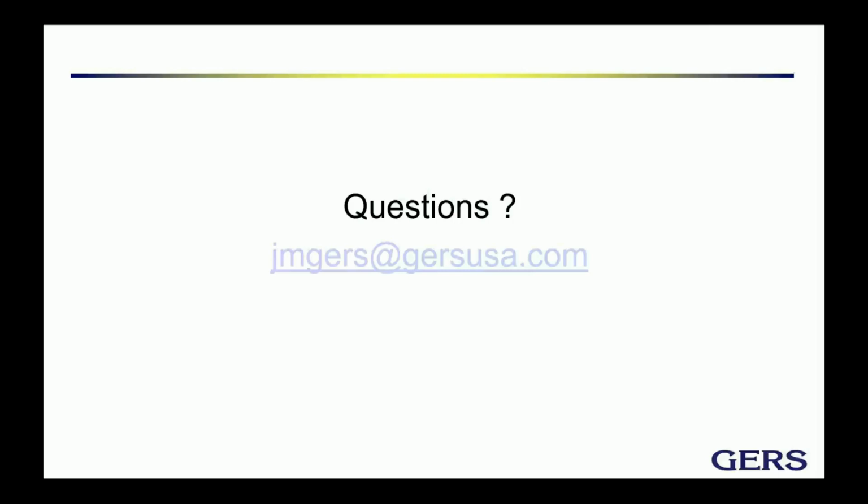All right, we have another question here. If a distribution system has a large number of solar farms or wind generation facilities, and we know that they operate according to the availability of sun or wind, how would you determine the relay setting groups? Okay, this is also interesting. It is supposed, of course, that the solar facilities will be kind of nearby. So it is customary, perhaps, to associate all of them to one setting group, because they should go on at the same time and off at the same time, late in the evening.